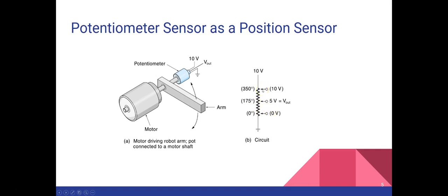Whereas if your wiper is over here on the top, then your power supply will go from there, and it will go to the output over here. So you see here how the voltage is changing evenly from 0 to 10 volts along the resistive element, and this wiper merely taps off the voltage drop between the contact point and the ground.